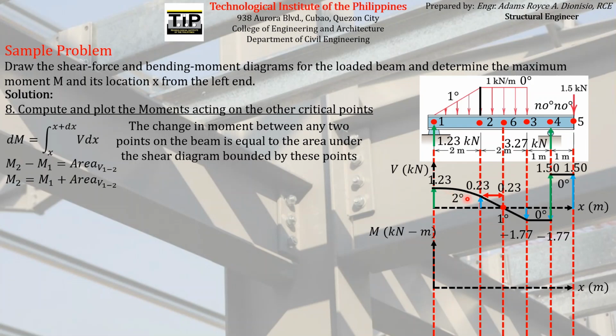as a second degree curve. And we can actually simplify the area of this second degree curve if we cut this whole area into corresponding rectangular and parabolic areas. So the dimension of the rectangular area is this. This is the height, which is 0.3. This is the length, which is 2 meters.